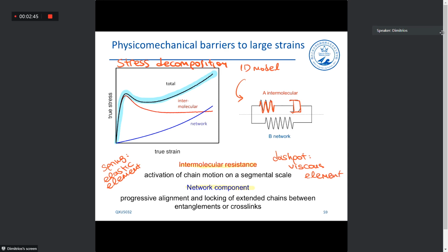I told you, in order to consider how a dashpot operates, you need to think of a bucket full of honey, and you're putting a piston in there where you're pushing the honey, okay? This is viscous. Your hand or the piston does not move freely within the honey, okay? And that is essentially a representation of how a dashpot operates.